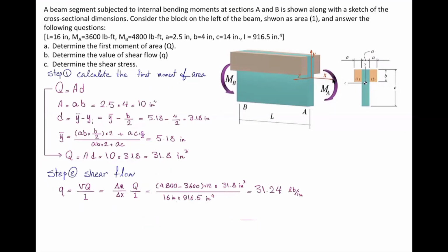Okay? Now I want to determine how much is shear stress. Shear stress is a shear flow divided by the thickness. Now we get to the second important question. What is the thickness that we need to consider for this problem?